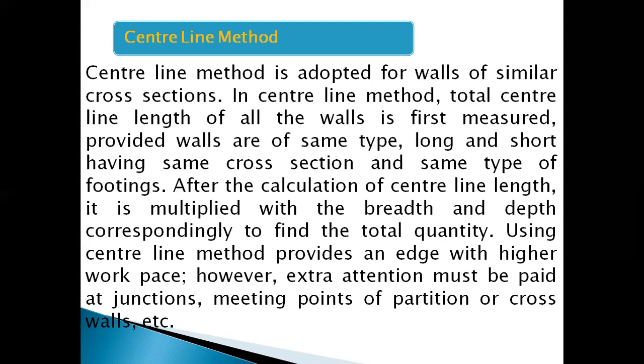After calculating the centerline length, it is multiplied with the breadth and depth correspondingly to find the total quantity. The Centerline method provides an edge with higher work pace. However, extra attention must be paid at junctions, midpoints of the partition or cross walls, etc.